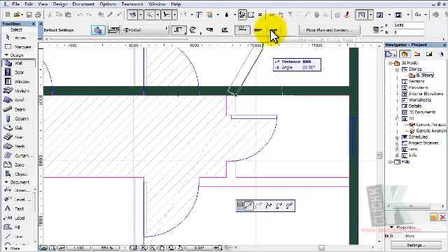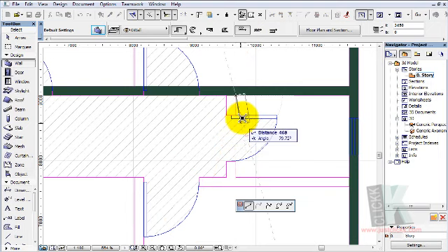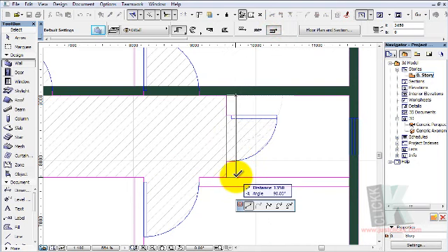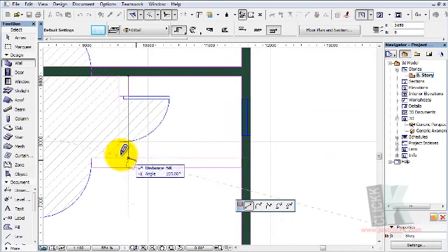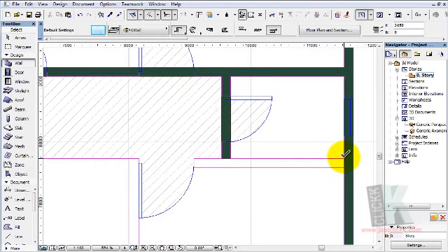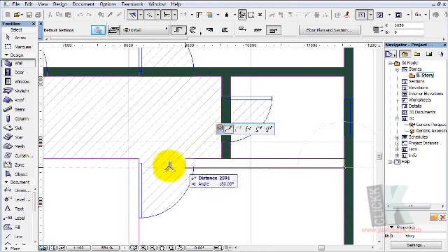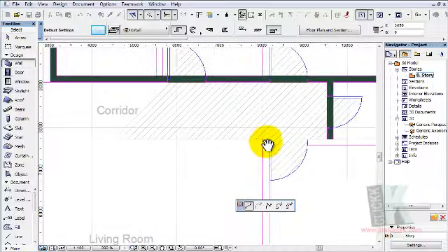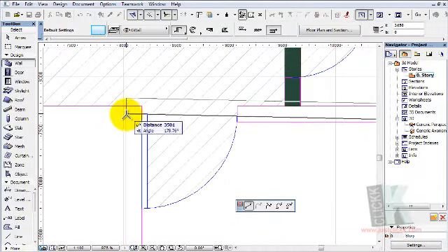Choose alignment position. Always remember quickly to choose your alignment, otherwise you don't need to escape to start this other side. Just choose your alignment here and it will reposition the whole thing exactly. So that's okay. Right click and terminate that there and start all over here, to take me up to this point.